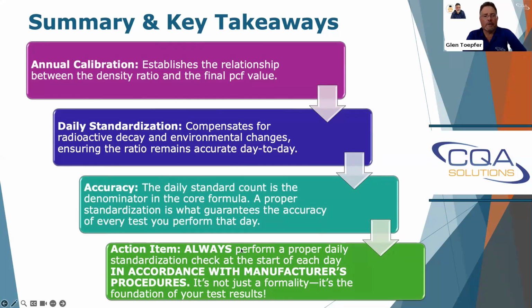And then an action item, always perform the standardization at the start of the day. A lot of people don't do that. And you see some results are erroneous because they haven't, and people scratching their heads. That's one of the biggest takeaways, the calibration and the standardization, doing it in accordance with the manufacturer's recommendations.